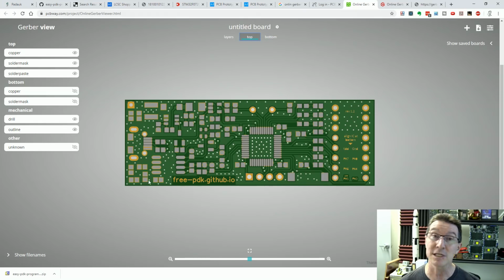As I said, this text here is not silkscreen. That's actually embedded, because you can see the gold color. It's not done in white or some other silkscreen color. That's actually copper on the board. In our case, we're not ordering a gold flash, immersion gold PCB, so it'll come up silver instead of gold, that silvery lead-free color. Same with the text over here. But anyway, that's a good Gerber viewer.